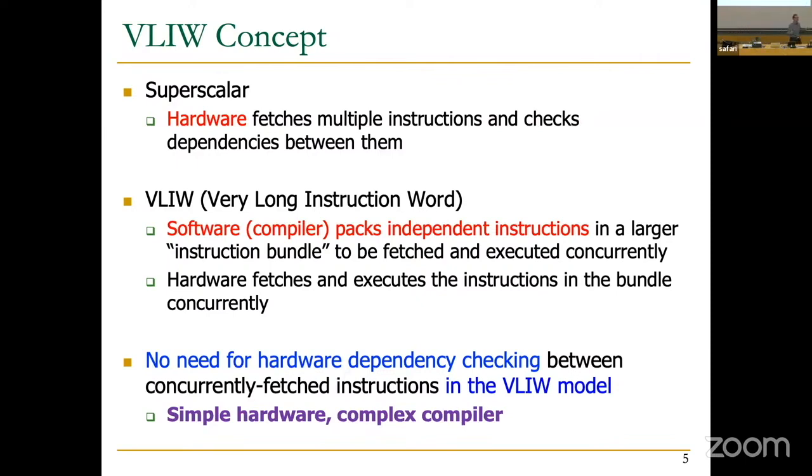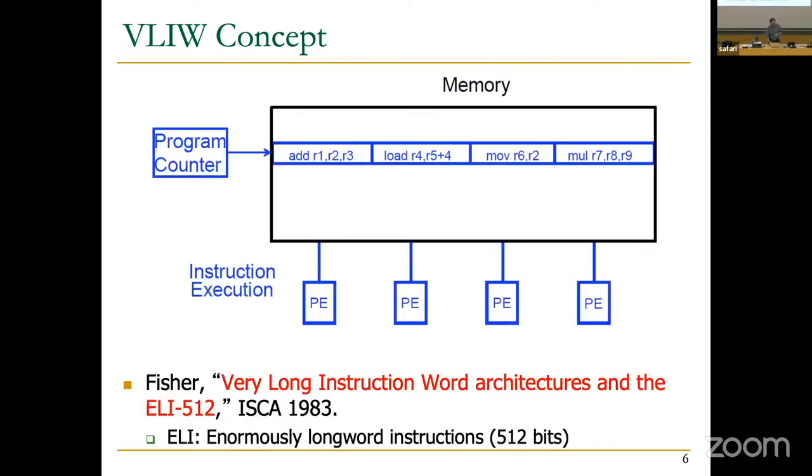Everything else is how do you make it work? Making it work is very difficult, basically. Okay, so pictorially, it looks like this. This is the VLIW concept. You have a program counter. When you get to that program counter, you don't get a single instruction like we used to. You don't just get an add, but you actually get 4 instructions in this particular case.